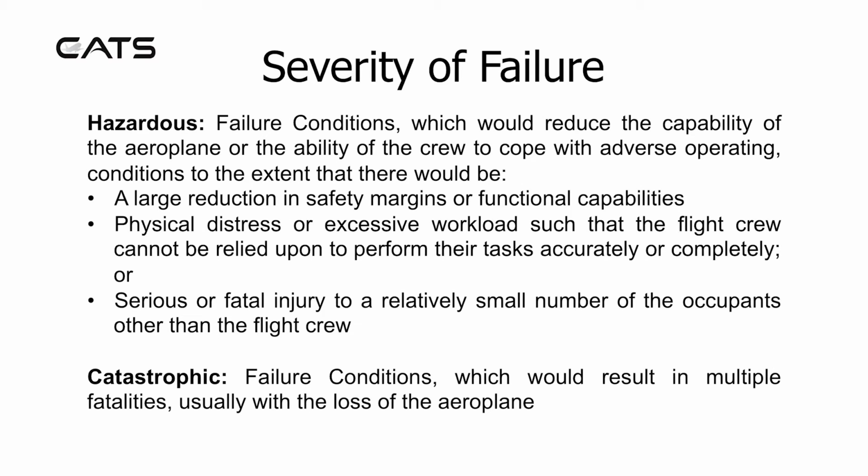Hazardous are failure conditions which would reduce the capability of the aeroplane or the ability of the crew to cope with adverse operating conditions to the extent that there would be a large reduction in safety margins or functional capabilities, physical distress or excessive workload such that the flight crew cannot be relied upon to perform their tasks accurately or completely, or serious or fatal injury to a relatively small number of the occupants other than the flight crew. And catastrophic are failure conditions which will result in multiple fatalities, usually with the loss of the aeroplane.